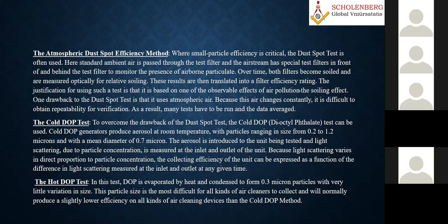The aerosol is introduced into the unit being tested, and the light scattering due to the particle concentration is measured at the inlet and outlet of the unit. The light scattering varies in direct proportion to the particle concentration. The collecting efficiency of the unit can be expressed as a function of the difference in light scattering measured at the inlet and outlet at any given time. So this is for the cold DOP test, but for this, there is so much mathematics involved.